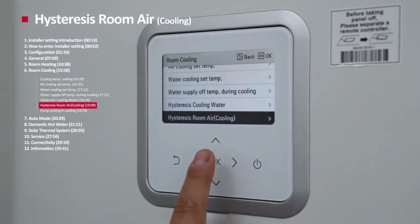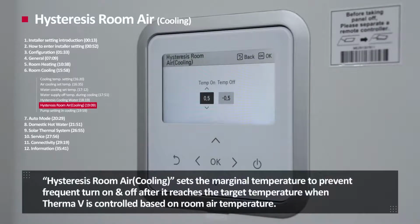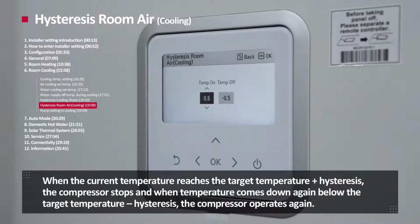Heat hysteresis, room air cooling. Heat hysteresis room air cooling sets the marginal temperature to prevent frequent turn on and off after it reaches the target temperature when Therma V is controlled based on room air temperature. When the current temperature reaches the target temperature plus hysteresis, the compressor stops. And when temperature comes down again below the target temperature minus hysteresis, the compressor operates again.